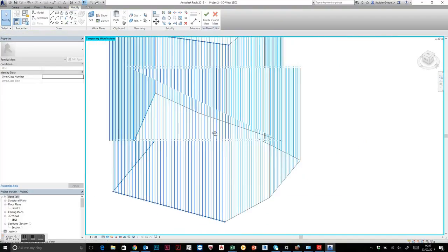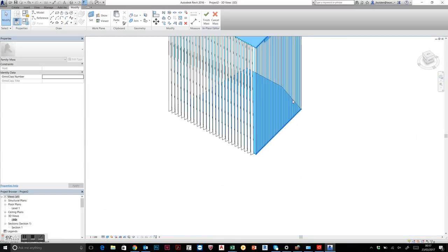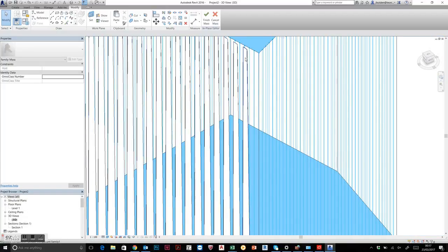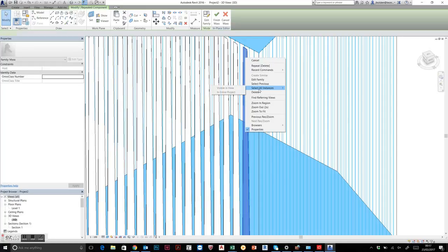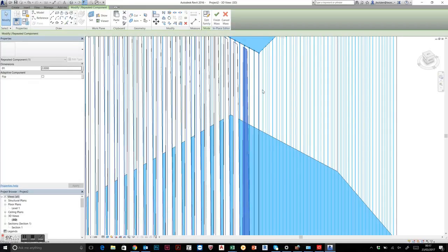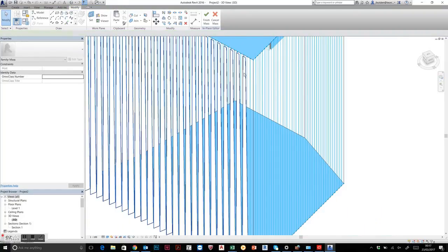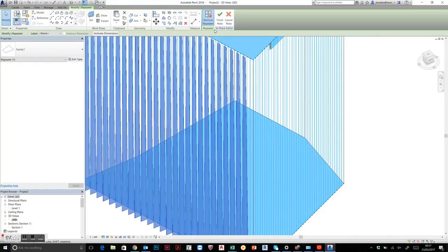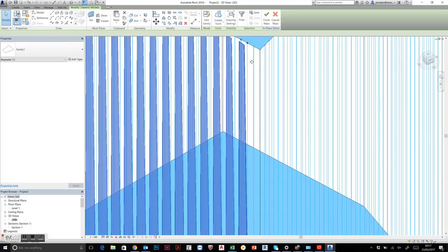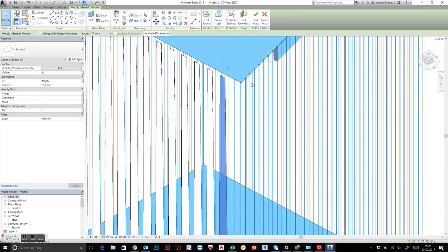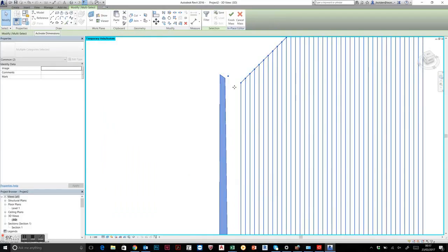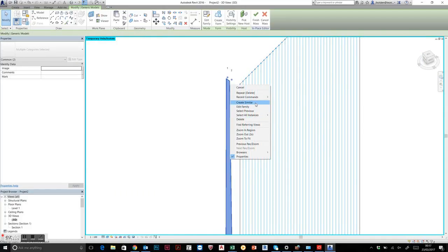So I've already got it mounted on here. I don't have to go searching for it. I can just click it, right click. I can't because it's a repeater. Just for speed's sake, I'm just going to remove the repeater board now. They want to go try it themselves because they're excited. Let me see. Select. Create similar. Create similar is your friend.